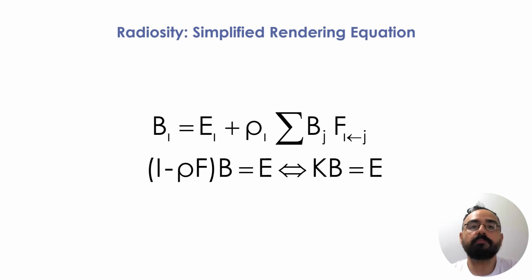But before we optimize, we must state how we calculate light. To model our daylight field, we use a simplified form of the rendering equation, the radiosity method. The total leaving illuminance Bi from surface patch i is the sum of the direct emission Ei and the reflected light from all surrounding patches j, weighted by their form factors F_ji and reflectivity ρ.